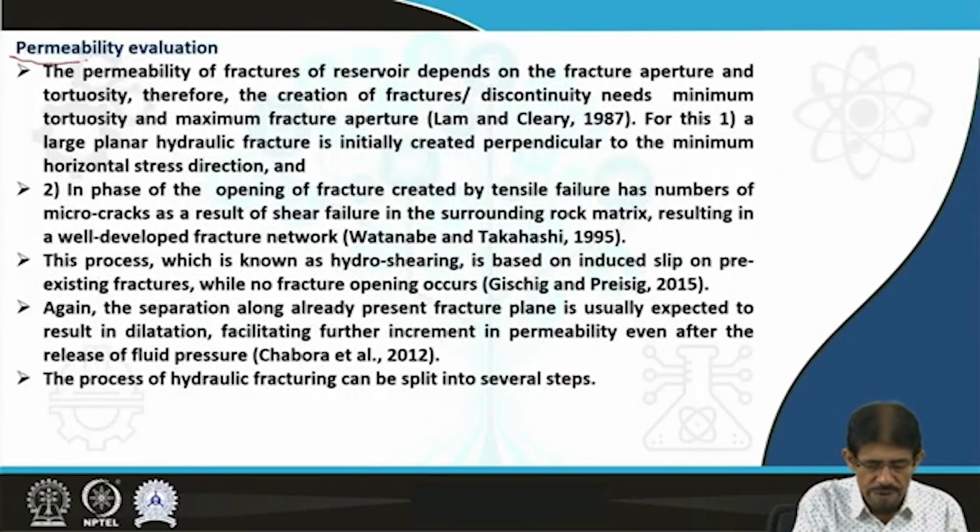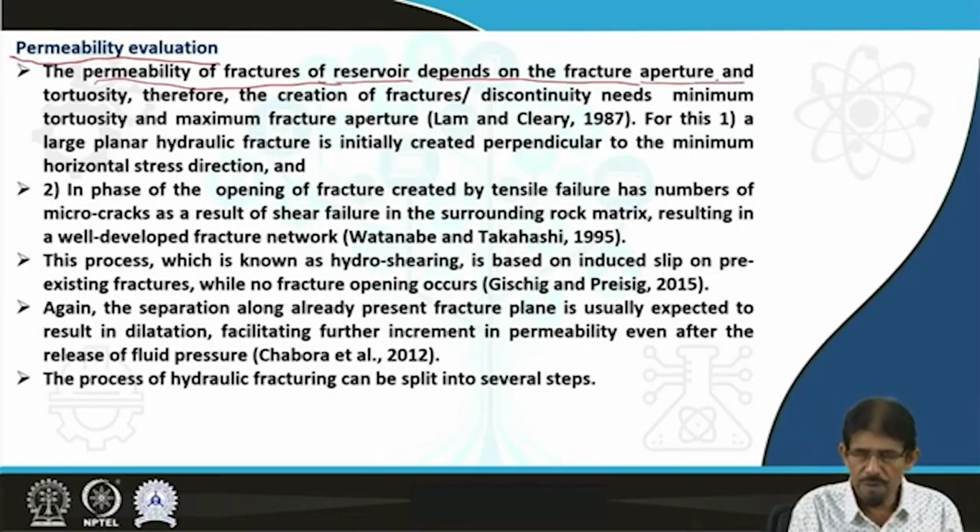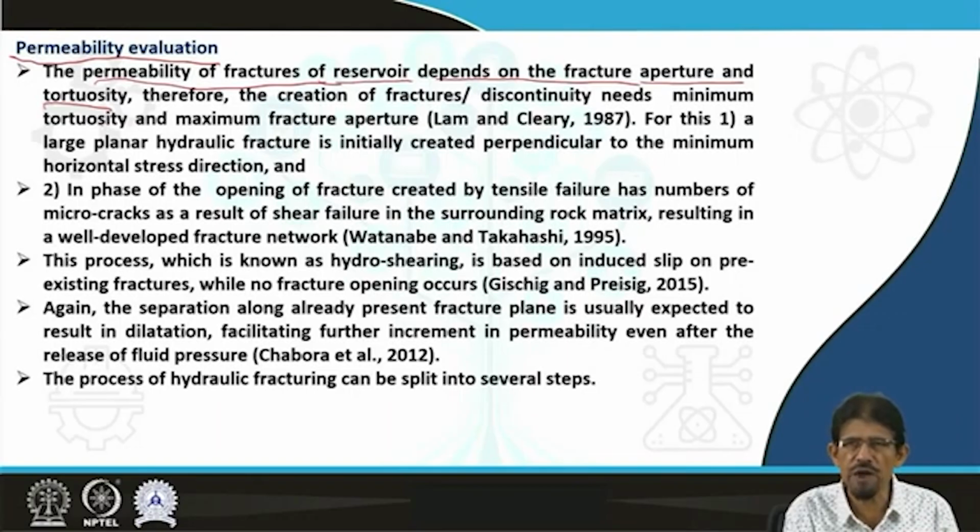Next important is permeability evaluation, because all the business related to extraction of geothermal energy is concerned with the permeability and availability of discontinuities. So the permeability of fractures or discontinuities of the reservoir depends on the fracture aperture, meaning the mouth, as well as tortuosity, because these fractures or discontinuities act as a conduit.